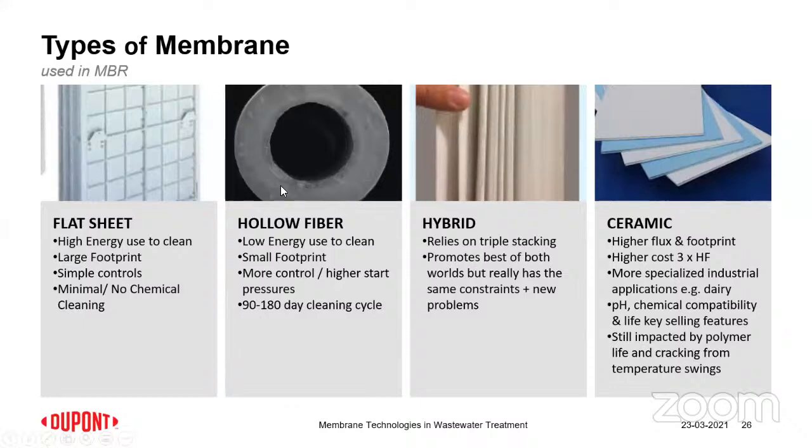Whereas with similar challenges in hollow fiber, if you have a broken fiber, you just knock that off and continue operation. Reducing one fiber does not significantly reduce the available filter area. So for practical reasons, hollow fibers are used in most cases.